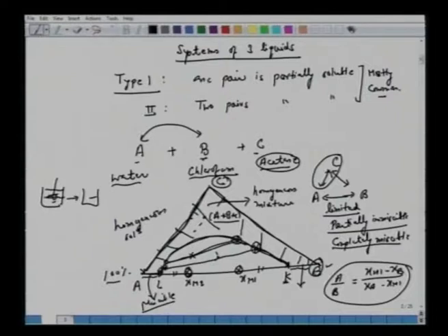If you recall, before this extraction, we had a discussion on distillation. So we had liquid and vapor, and of course we had only binary components. So we had this phase diagram, liquid and vapor, and there, if you choose a fixed temperature and draw this horizontal line, and you have a mixture of liquid and vapor, allow them to come to equilibrium, then there is separation. Vapor is rich in one component, liquid is rich in another component. But you have both A and B in the liquid as well as in the vapor phase. So that's a phase diagram.